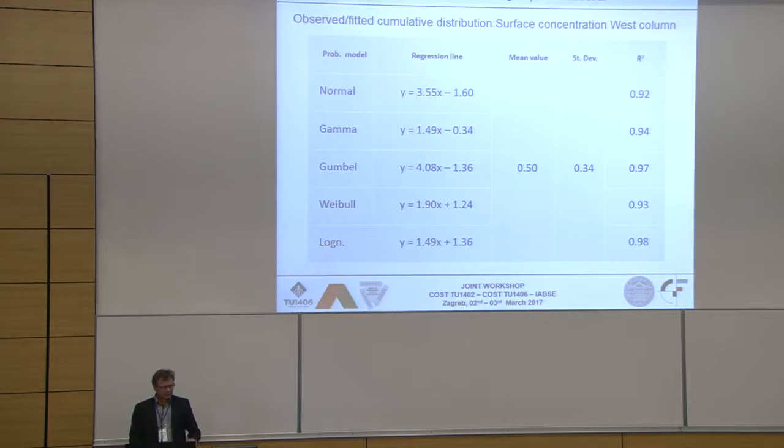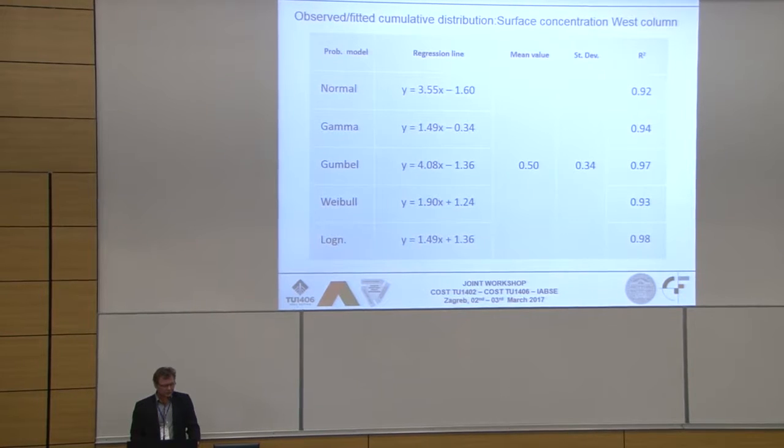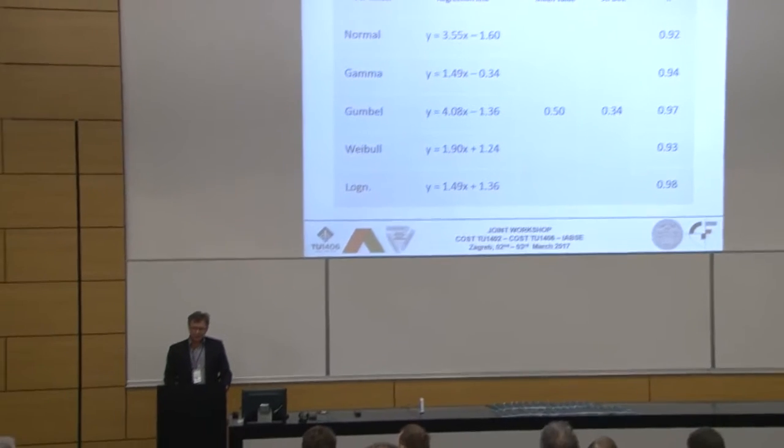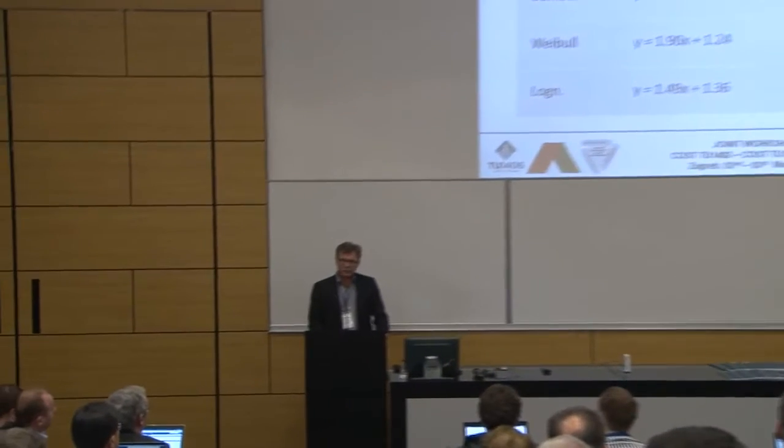There are wide differences: the front side towards the wind has less surface concentration than the leeward side, and this is due to the rain and the wind, which wash the front side. On the leeward side you have turbulence, which means that you have chlorides put on the surface of the leeward side, more than the front side.